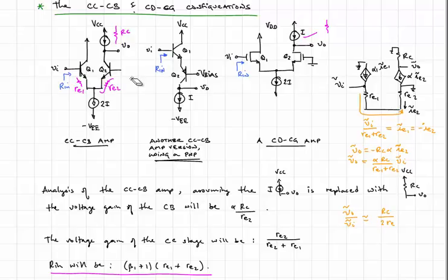Any differential voltage is what actually causes amplification. Although we haven't looked at it yet, when we lift the base of Q2 from ground and consider it as a separate input, and look at VI1 minus VI2, we'll see that this is actually a differential amplifier, and that will be the basis for the front end of an op amp.